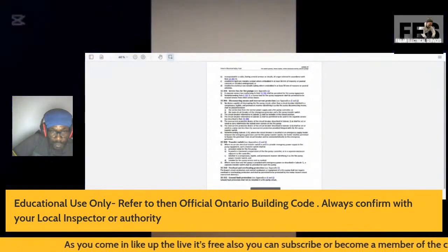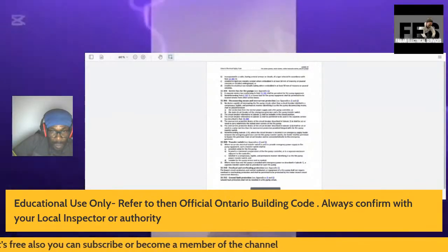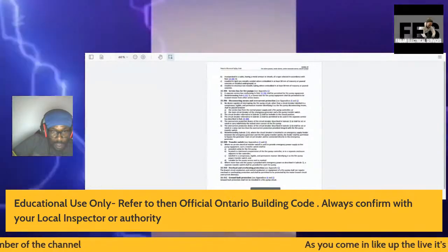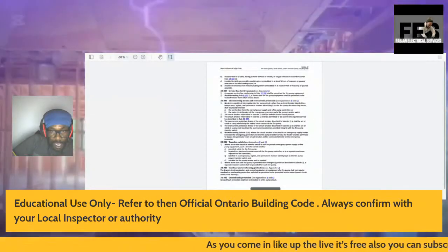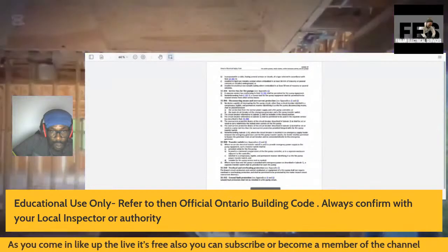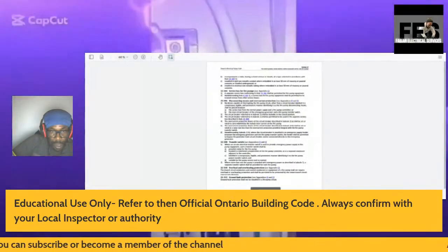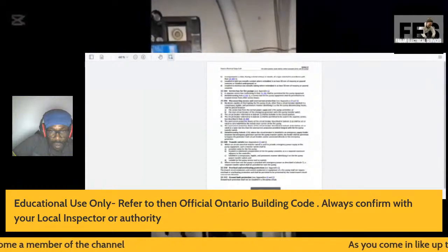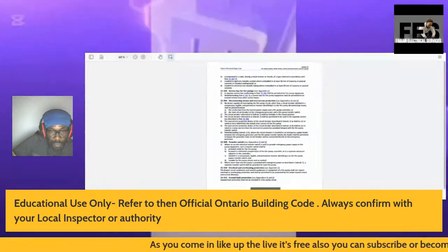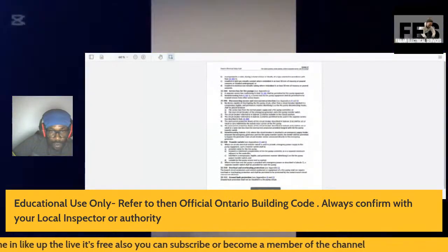The overcurrent protective device of the circuit breaker described in Subrule 1B shall be set or rated at a value not less than the overcurrent protection provided integral with the fire pump transfer switch. Notwithstanding Subrule 1B, where the circuit breaker is installed in an emergency supply feeder between the emergency generator and the fire pump transfer switch, the feeder shall be permitted to bypass the generator main circuit breaker and be connected directly to the emergency generator.